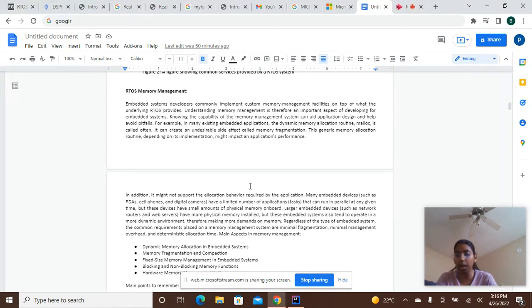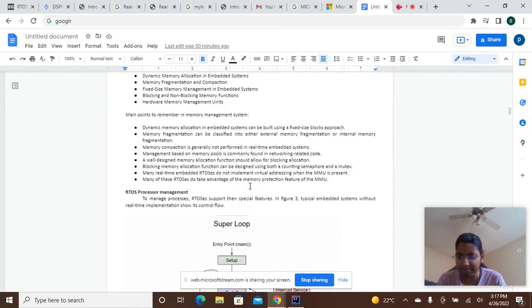An RTOS system utilizes memory compaction using a memory location map. The memory compaction is allowed by a task owning those memory blocks, and it refers to the blocks using virtual addresses of its memory. Memory compaction is not permitted when tasks are holding physical addresses.